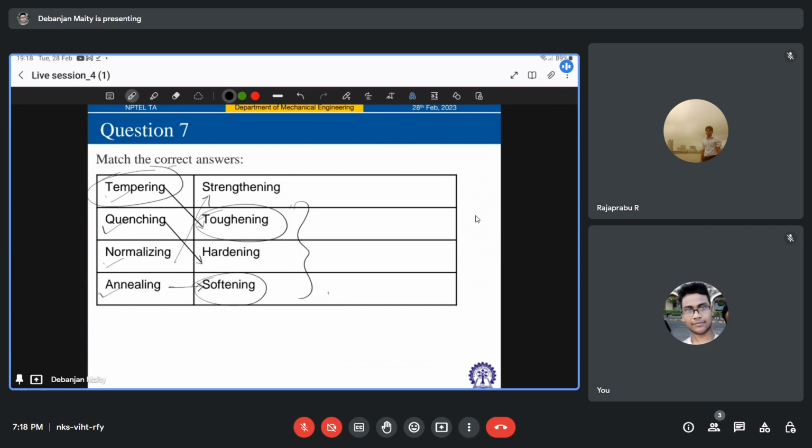Austempering is done by quenching the steel from the austenitizing temperature in a molten bath, with the temperature kept just above the level of martensitic transformation, and the holding time in the bath is such that the austenite is fully transformed into a bainite structure.